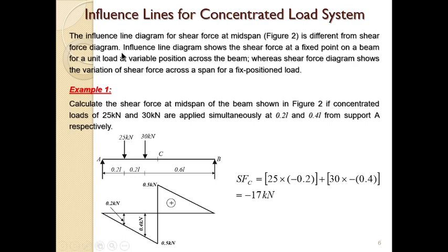You need to take note of this, that the influence line diagram for shear force at midspan is different from shear force diagram. The influence line diagram shows the shear force at a fixed position on a beam for a unit load at variable position across the beam.